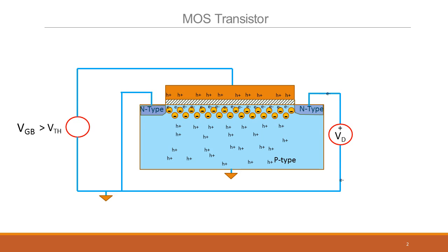Since you put in a positive voltage here, electrons will go from here to this side and they constitute a current, in the opposite direction to the flow of electrons. This n-type is now called a source because it is sourcing the electrons. The electron, remember, went through like this. So this is sourcing the electrons, the minority carriers, or what you call the majority carriers in the inversion region. So it is called the source.